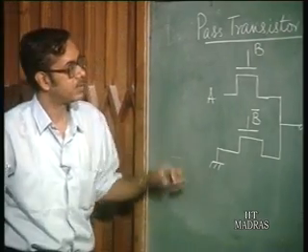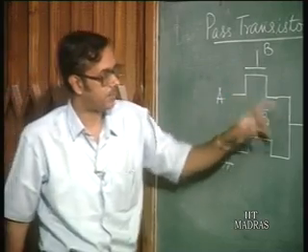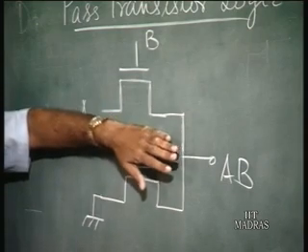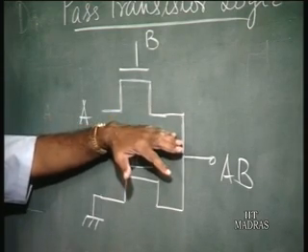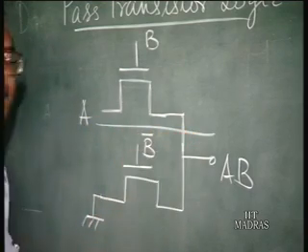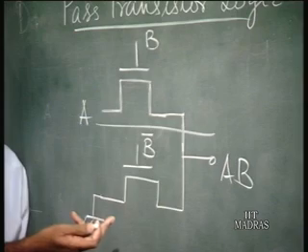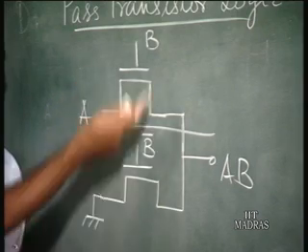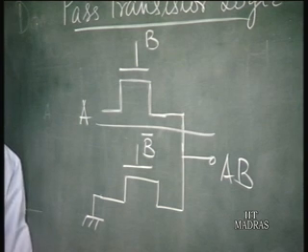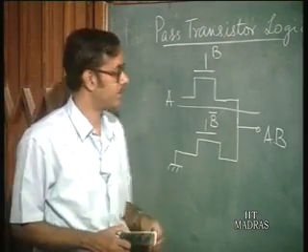So this is one example we have given, but we must always be careful when we use this for logic circuits. You cannot just say this is A and B, because when B is 0, if we just use this block here, the output would be undefined. So you must always take into account that all the possible input combinations are accounted for. That is one constraint you have to think of.